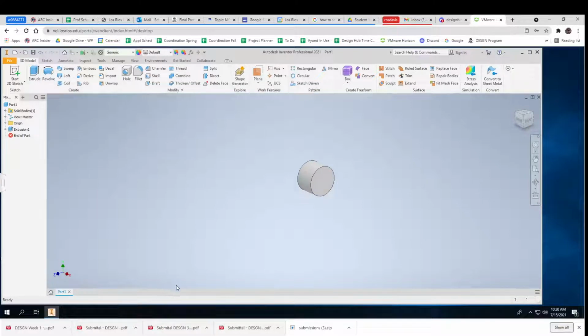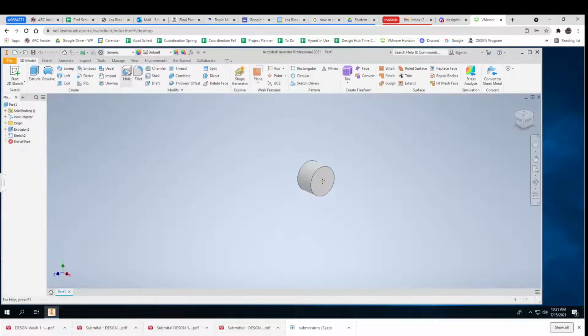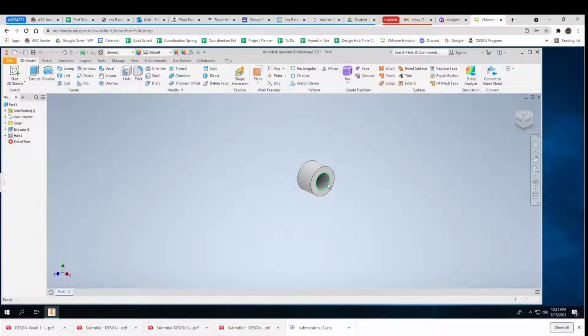So that's it. And then there's a hole in it. And the reason I'm going to make it a hole is it's got a very special tolerance. I'm not going to worry about the tolerance right now, but I can go right there to that end and put a point on it. I could also draw this thing, but I like to do it this way. And then I'm going to say that there's a hole there, and the hole has a diameter of 3.52. And I can look at all the tolerances on it and everything later on.